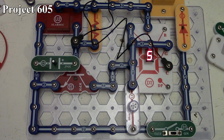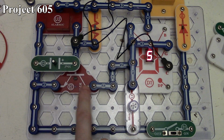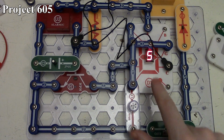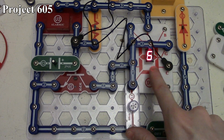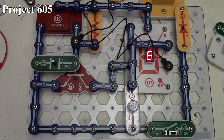So when we turn it on, it starts off with S and it alternates back and forth between S and E. And as our alarm IC output goes on and off, it controls the output to our NPN transistor, alternating between our one segment here and the segment on the other side. And by that we can get it to switch between showing an S and an E on our 7-segment LED display.